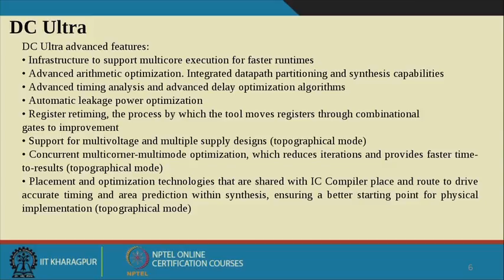As I said previously, floorplanning, placement, and all these things can be done at an advanced stage. Though I am not using the physical design part, that is, I am not using IC Compiler, in the earlier stage of synthesis itself I can see the results of how my circuit is going to perform after working with IC Compiler, in place and route mode. So that can be done.